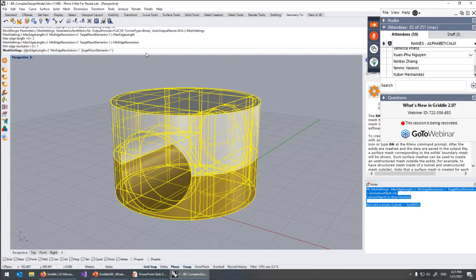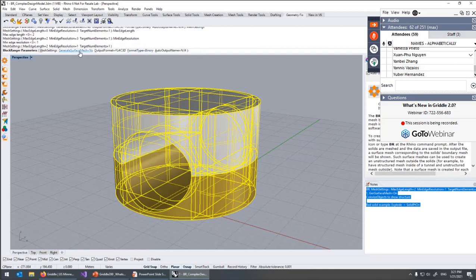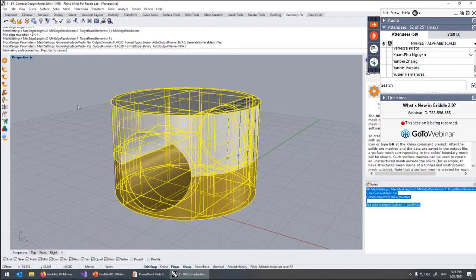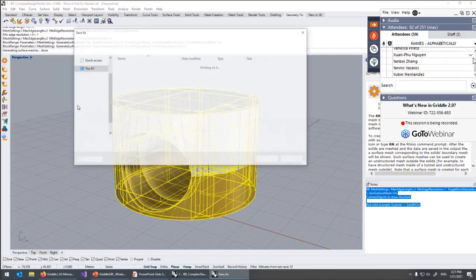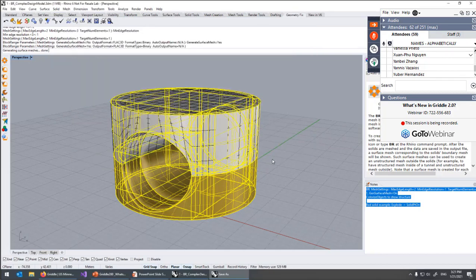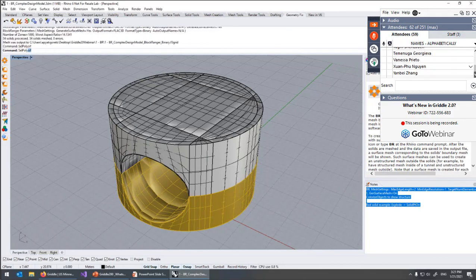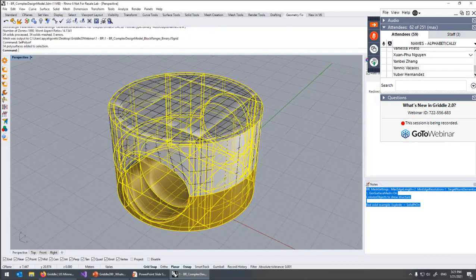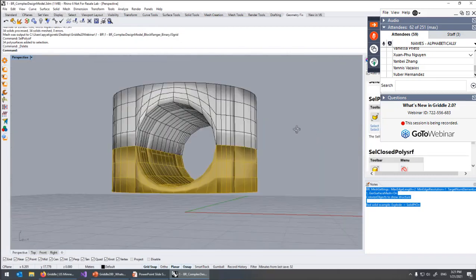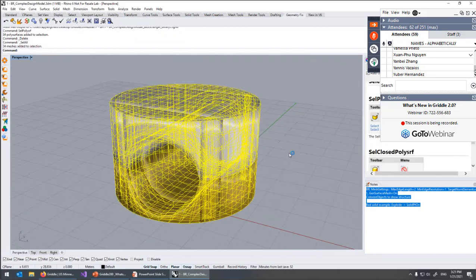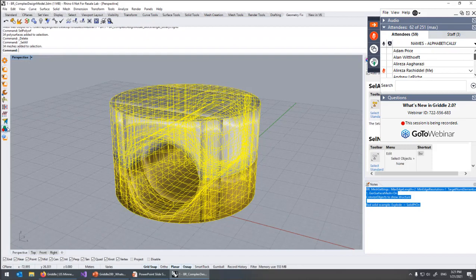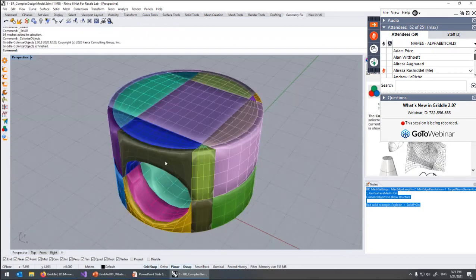So it can be useful for novice users. Well, let's proceed with meshing. I'll also select Generate Surface Meshes. And in a few moments, we're going to see how the surface meshes look. Let's save the file. This is the volume output. Let me select the polysurfaces and delete them. We now just have meshes. You can see that everything is meshed properly, and each mesh corresponds to a separate solid block.